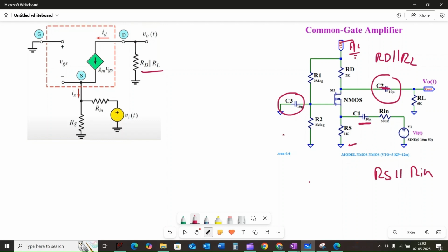By defining the current and applying the KCL, we can establish the equation relating the drain current ID, the input current In, and the current through the resistor as IRS. We can express this current in terms of VGS, Vi, and the resistor value.